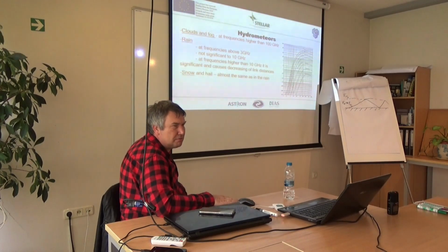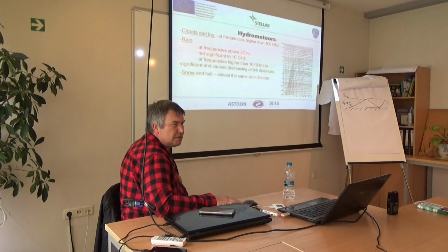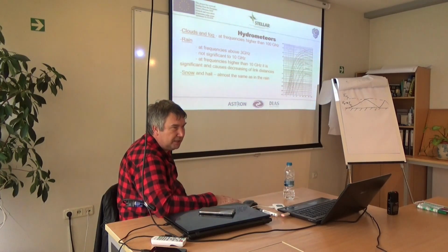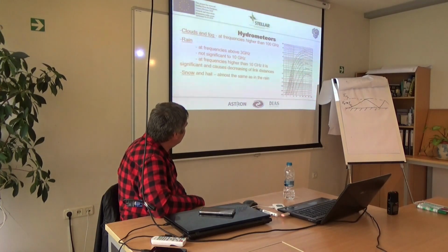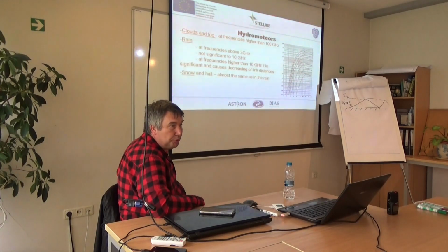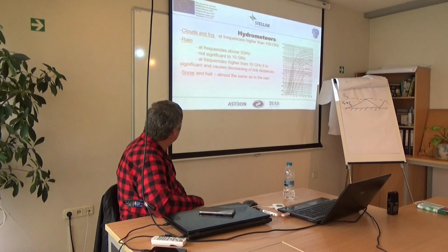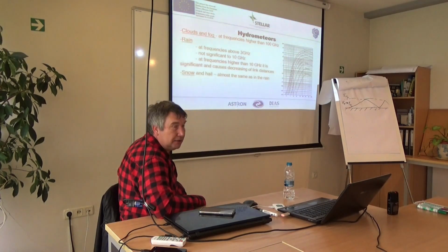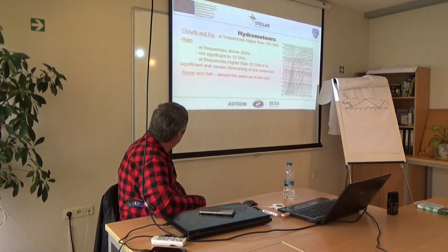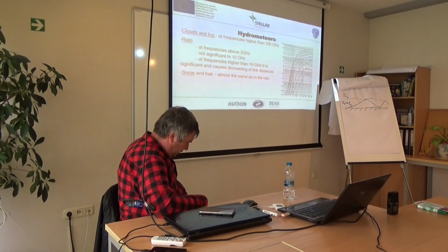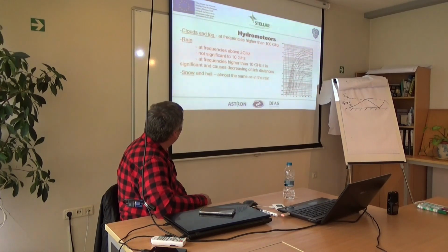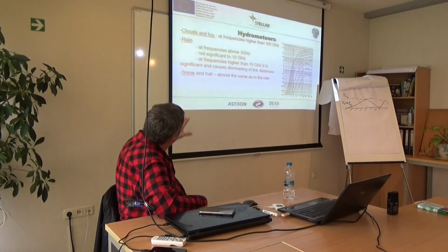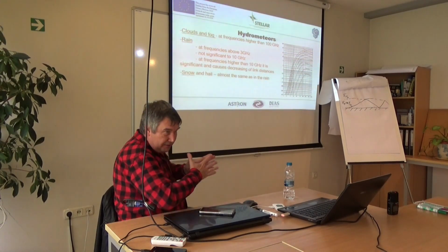Satellite TV uses frequencies around 12 gigahertz, a little bit higher than 10 gigahertz, and in this case the attenuation is high, and this causes decreasing of the link distance.